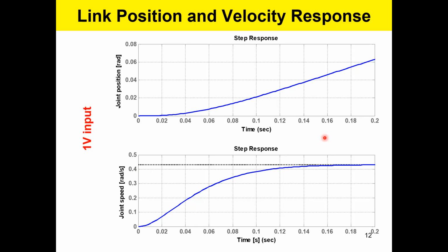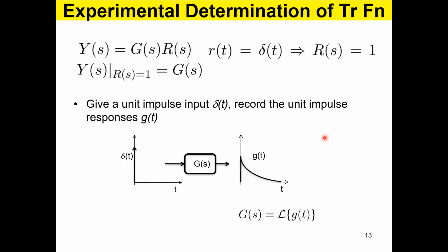You change the input voltage, right? So then you can have some sort of communication from motor speed to the input voltage. And that is where things get more interesting. That is where controls actually start. Take this output signal, that is the speed of the arm, and then feed it back to the voltage to adjust the voltage. So that's going to be the controls. Now, before that, I want to show this to you.